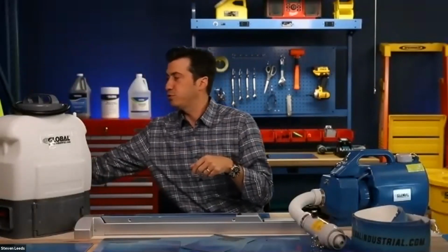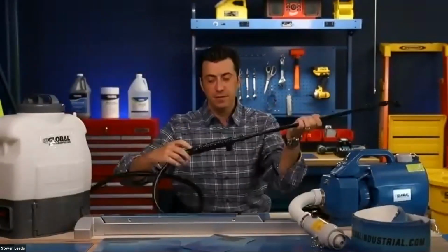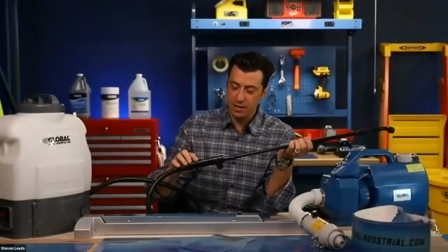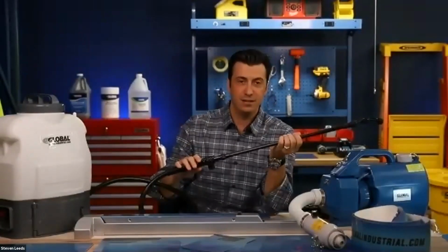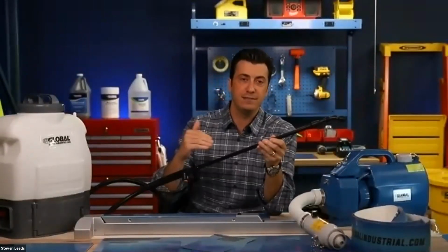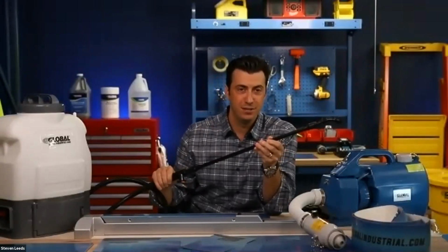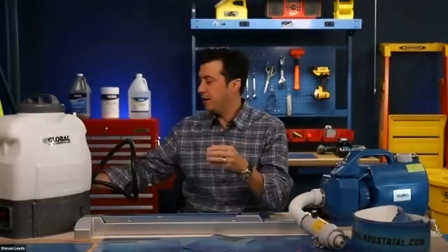So now what an electrostatic sprayer does is, as chemicals move through the nozzle, as you can see right here, this positively charges the ions. So as the chemicals are dispersed, they are now attracted to negatively charged surfaces. So what that means is those chemicals, as they come out, they now wrap around a surface.